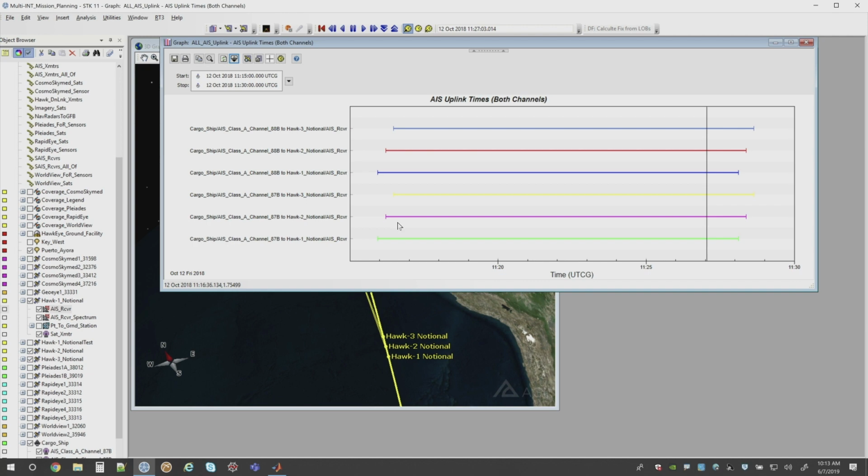So what we can look at next is one of the location mechanisms, which is looking at Doppler shift crossing. Essentially, as the signal Doppler shift varies as it crosses 0, that's going to be the time of closest approach to the emitter of that signal.